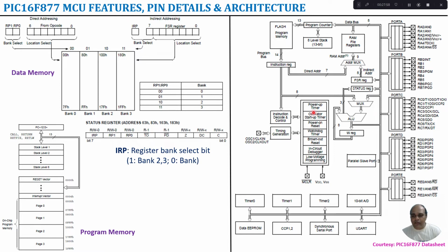Both the power up timer is for power stabilization, it provides the timing for power stabilization. The oscillator startup timer provides the time for oscillator stabilization. So during both these times, a power on reset will be applied so that the microcontroller will be in a reset state.